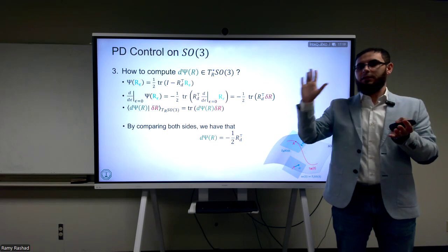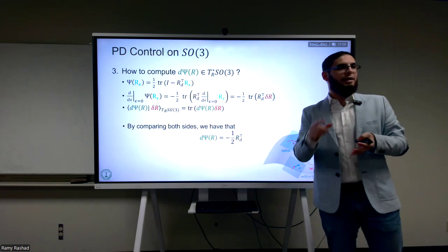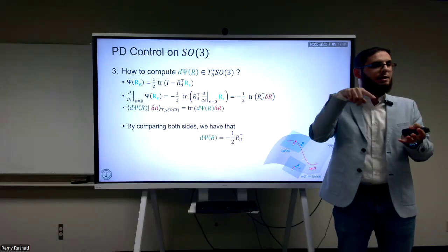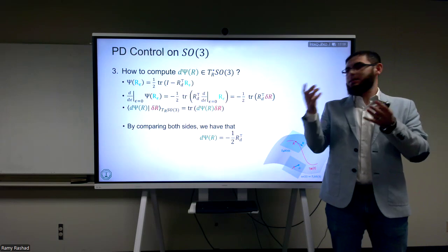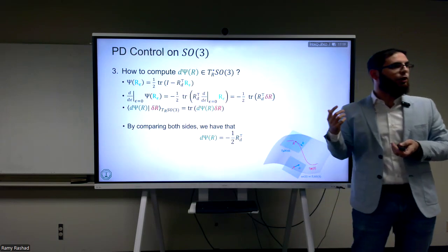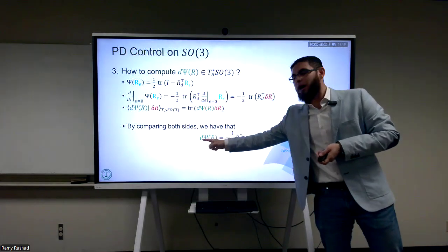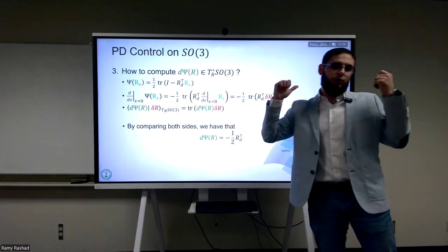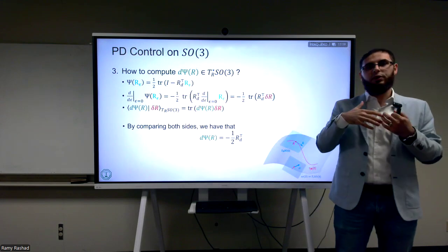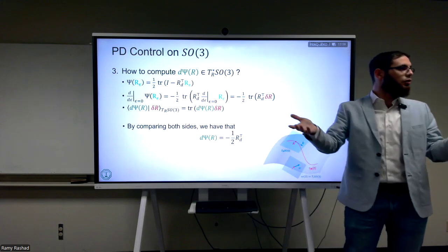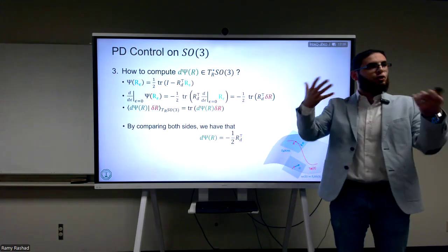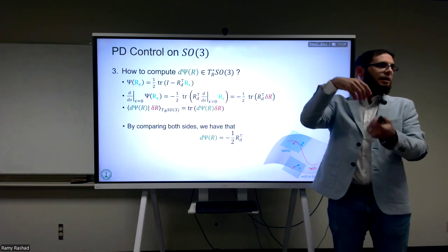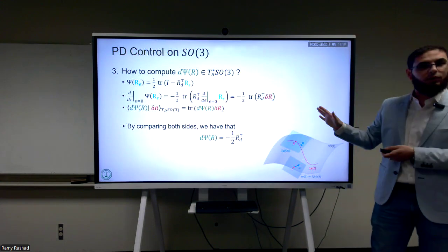So we simply had that the codifferential was in R3, and we said that our proportional control input is equal to minus Kp multiplied by the gradient. If you go back to when we talked about the point mass, the controller was equal to minus the gradient. The reason is that this gradient lived in R3, so it's easy, R3 is equal to R3. Here, because of the geometric structure, this is a 3x3 matrix, so we need to transform it into three numbers that in the end will correspond to the torque. This is what we're going to be trying to do.